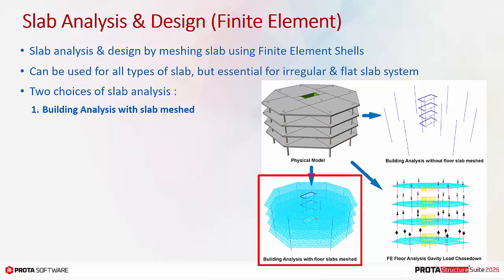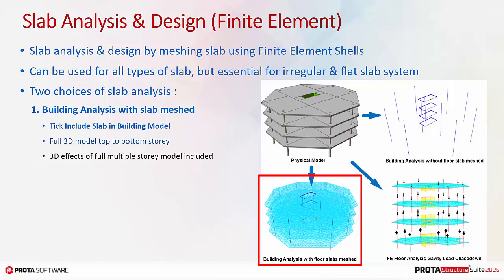Building analysis with slab meshed. Tick includes slab and building model. This will assume a full 3D analytical model from top to bottom story. Hence, inherent 3D effect of multiple stories is included. Gravity and lateral load effects can be obtained.